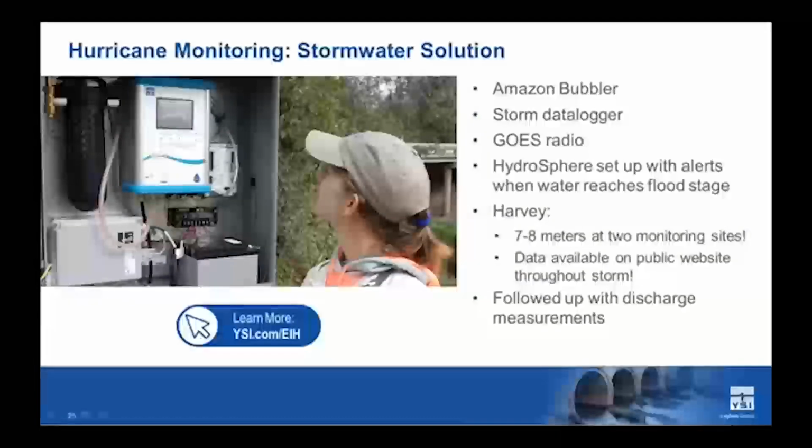So this is how they are measuring stage in a continuous fashion without someone having to be on site all the time. They, of course, had a storm data logger, and in this case, they had a GOES radio for doing transmissions. They were using satellite. They have the data going up to Hydrosphere, but in the case of EIH, they're actually processing that data and putting it on their own website, so it is always available to the public, and you can learn more about that at their website. This is battery powered. That is critically important, and this is also being solar recharged.